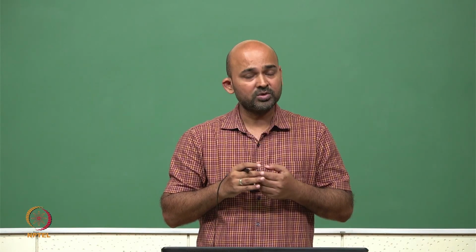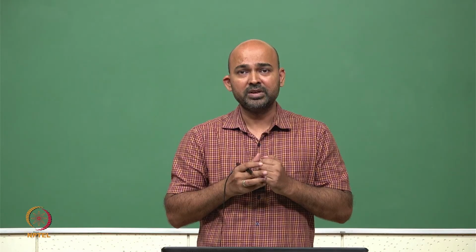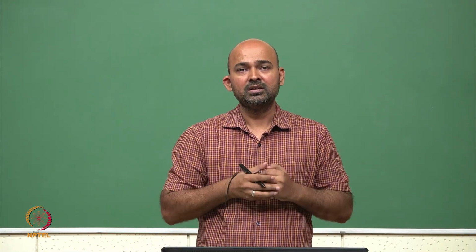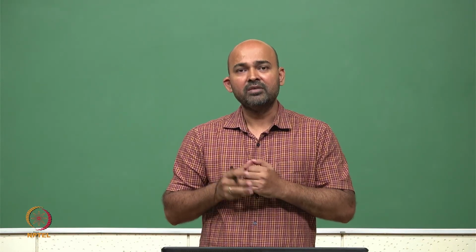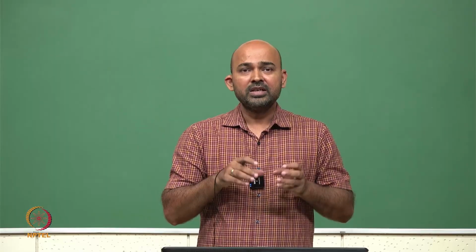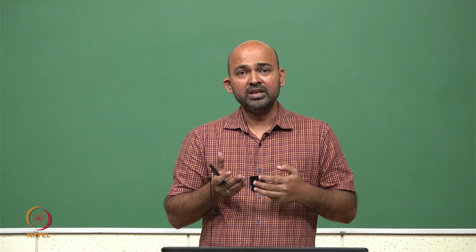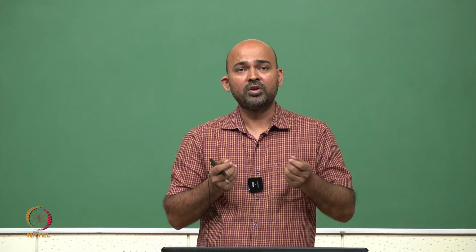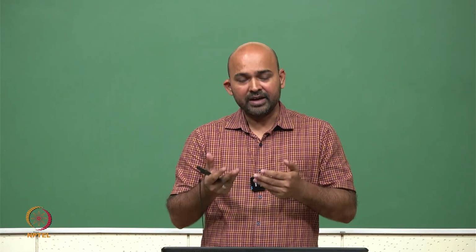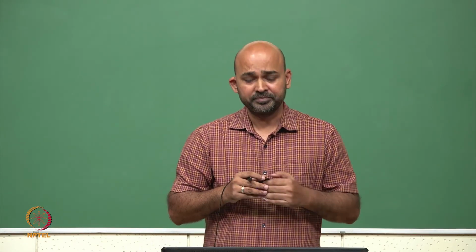So this is still a ratio-less design, and this offers sometimes faster switching speed, because the load capacitance is much lower at the previous stage, because we have fewer transistors. However, in dynamic logic gates, we have a pre-charge clock, which is an extra circuit we need. There is extra routing for a pre-charge clock for all the gates. So that adds up to the power consumption of the overall system.